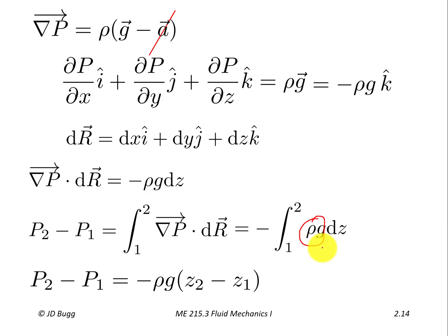So that's certainly a very good assumption. But realize we're also assuming that density is constant. So we would have to be careful about doing this in a case where the density is changing or where there's some stratification of some kind where the density isn't constant. So you do need to be careful about both of those assumptions.